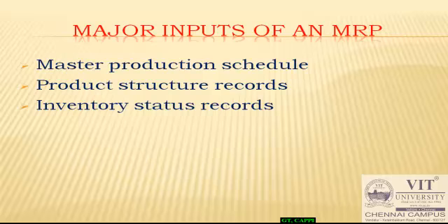Master production schedule, in the sense of how much we have to produce and what the components requirement is, that is the scheduling date. Okay, we get the order today, we need to give it to the customer within 2 or 3 days. So before that we have to schedule the entire process. According to that schedule only, you can plan for MRP, that is material requirement.